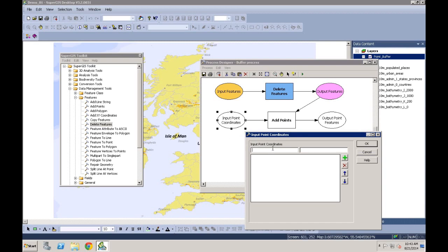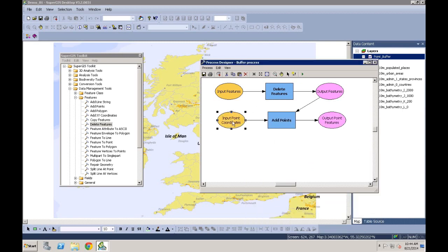You can add in a default point coordinate as a default value, which I'm going to enter as 4.10907589, and y will be 5.684027779, with the north. You have to be very careful to press this plus sign to add in the default value and press OK. So now you can see the process has been activated.